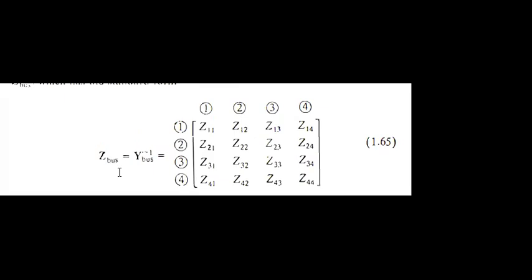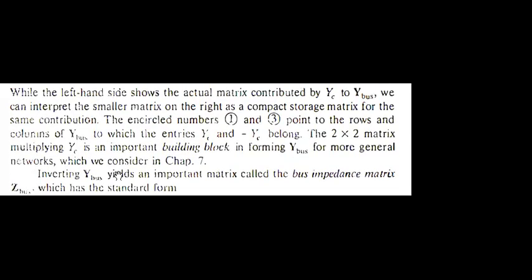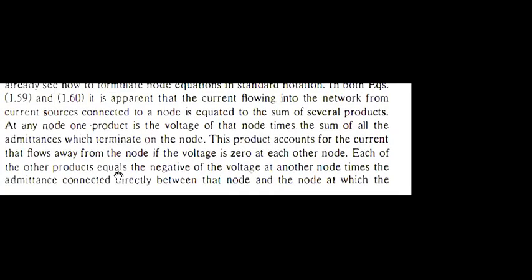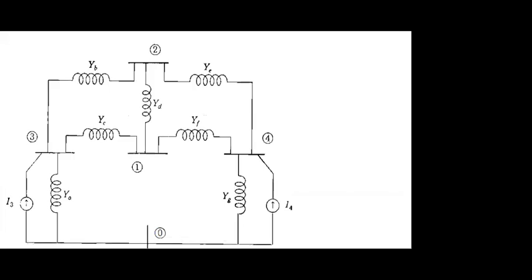How can we generate Y bus from the admittance diagram? Say, for example, if you have been given a simple circuit, can you shift that information to its equivalent admittance diagram? In general, circuit diagram information will be given in terms of resistance or reactance or impedance, right? So for the impedance diagram, you have to take the inverse to generate the admittance information.